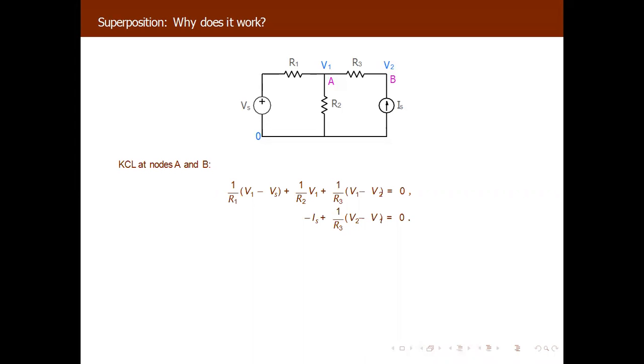If we are applying KCL, we are having the values by using node analysis. We are having nodes V1 and V2, and we can consider this as the reference node. So we can calculate for V1 and V2. V1 is connected with this, this, and this, so you will get 3 equations here.